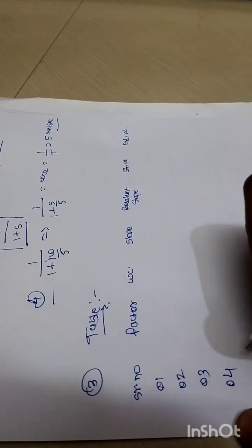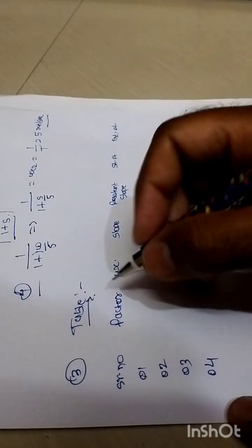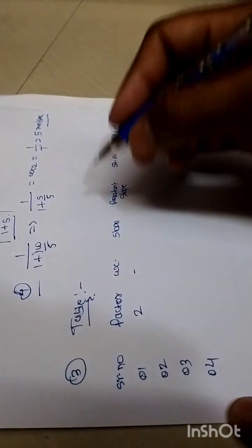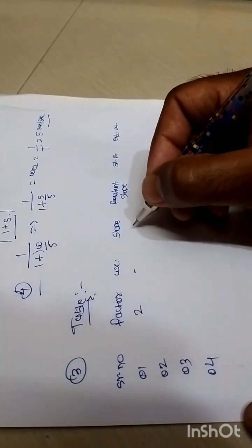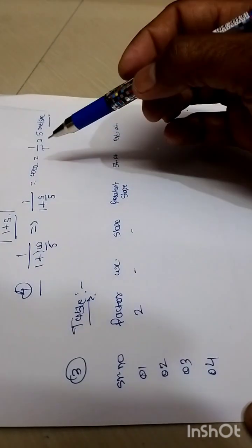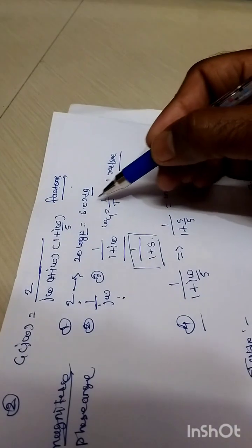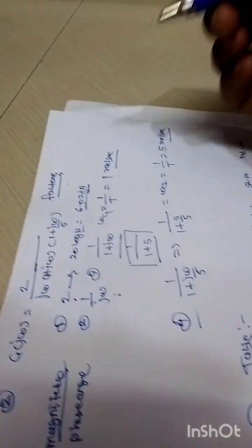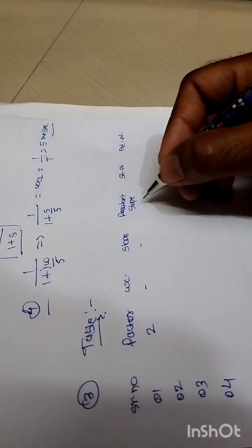So as we are having 4 serial numbers, out of that 4, the first one is this constant term, so it has nothing to do with the corner frequency, right? Again we don't have the initial slope, its resultant slope is already tabulated. How much is it? It is 6.02 dB by using this formula 20 log k. So it will become